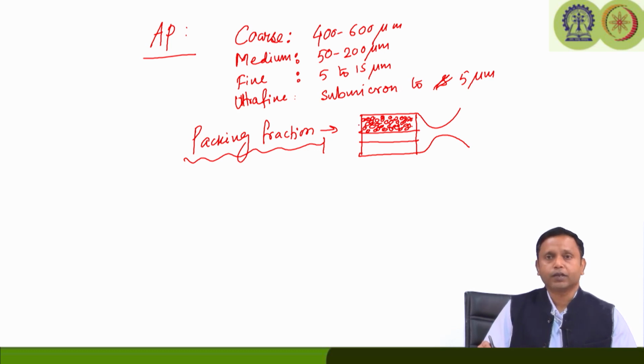So, processing complexity will increase if we add too many solid particles within the propellant matrix. That part we must take care of, in order to maintain the proper physical or mechanical property of the grain, as well as the ballistic property of the propellant. So, there is a trade off, and accordingly the solid fraction is chosen.